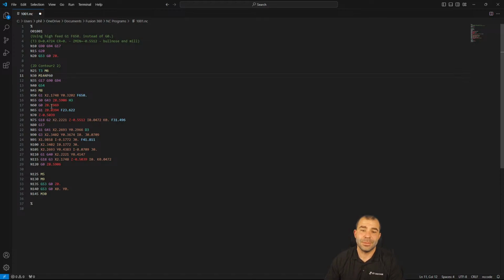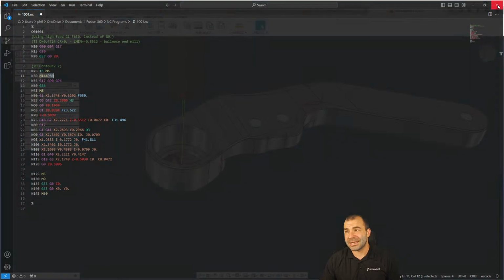It's still going to work the same because you're doing X, Y. In your case, it would be either XZ or YZ based on what you're doing. Now, if you're going to cut a female spline versus a keyway, you could go in and, with patterning, use that A axis to rotate and cut it in different areas. Again, you can lock the spindle. Some machines get very fancy, where you can orientate the spindle to different locations. I've modified a post for somebody to do that, where instead of spinning an A or a C axis, we actually orientate the machine. But we would do quite a bit of post work to get that to work.